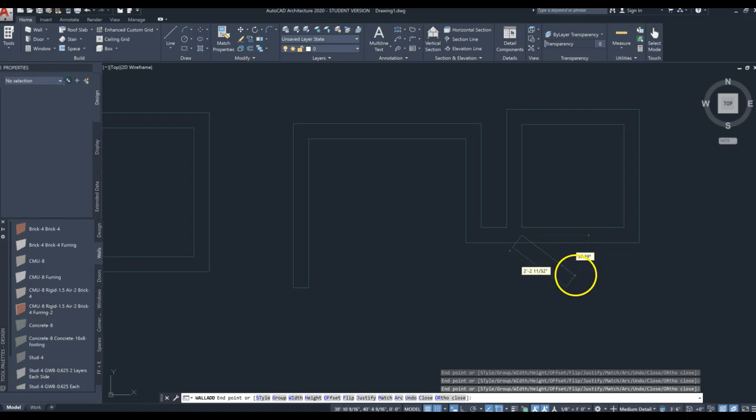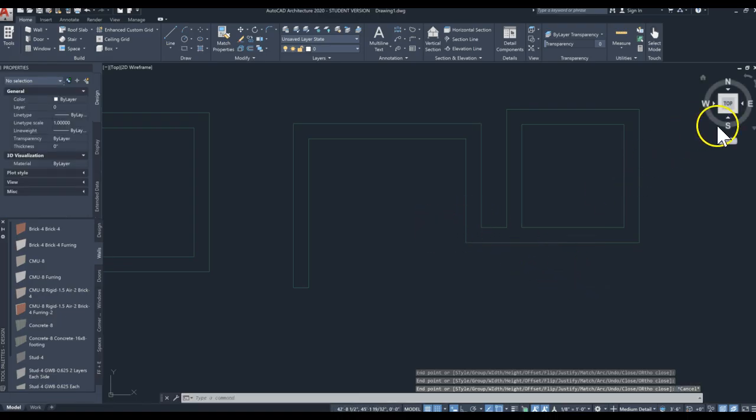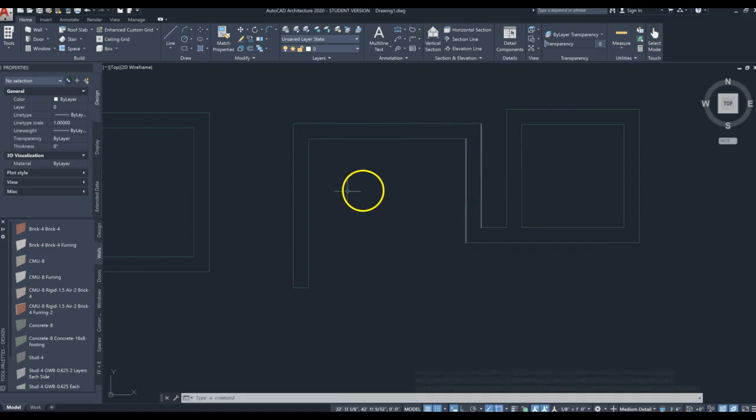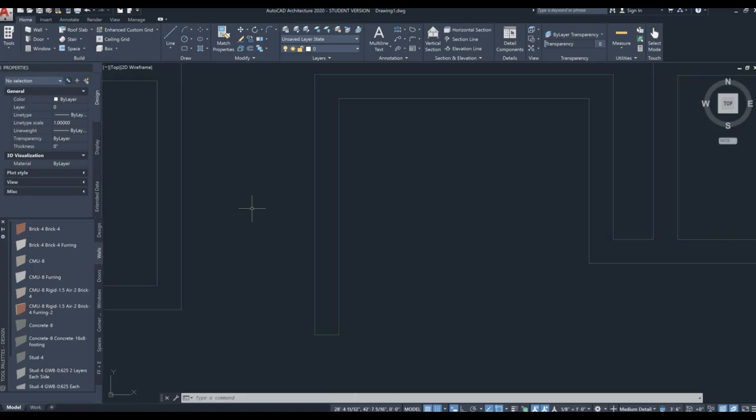And then hit escape when you're finished building walls. Now, you may have noticed that I'm moving around during this process. My screen was changing. On your mouse, scroll forward with the scroll bar and then backwards, and that's how you zoom. Try this. Click the scroll bar down, depress the scroll bar, and hold to drag around. That's pretty cool.